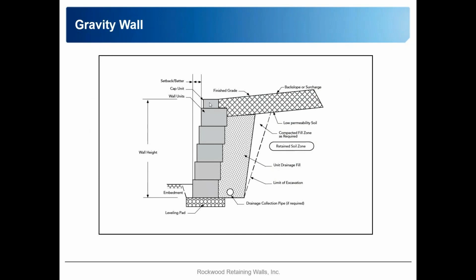So you would think though, well, okay, what if we had, manufacturer recommendations is to bury at least 6 inches of block. That's 6 inches of block, it can't tip over. So why is that considered part of the overall design height? Or conversely, we might even have as much as a foot or 2 feet of block buried. So our exposed height might be 8, but we could have 2 feet buried below. Our design height and what we would have to look at for engineering that wall would be the 8 feet that's exposed plus the 2 feet below.